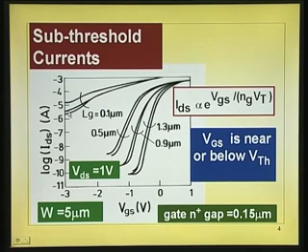It is not a linear scale that we are seeing. If you see in the log scale, as I come down below threshold voltage, it is almost linear. Linearly falling in the log scale means the characteristic is falling exponentially. Ideally, once you reduce the voltage below threshold, you would expect it to fall very steeply. That means it could turn off.